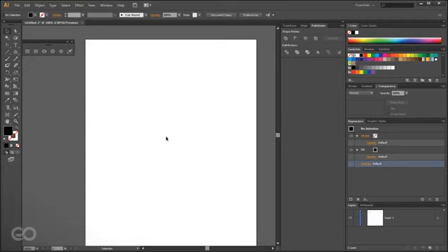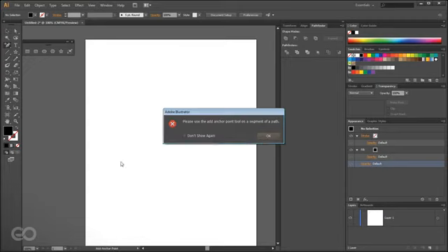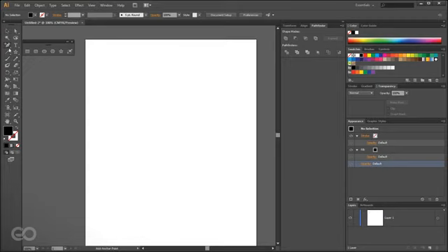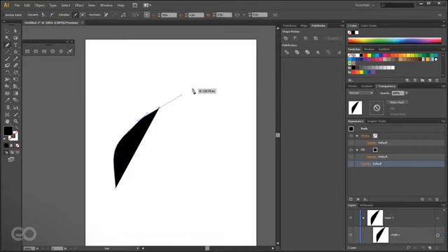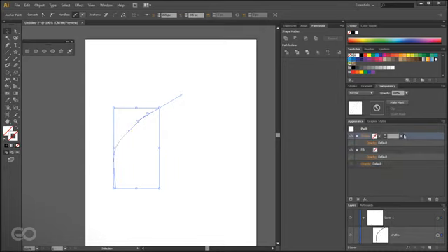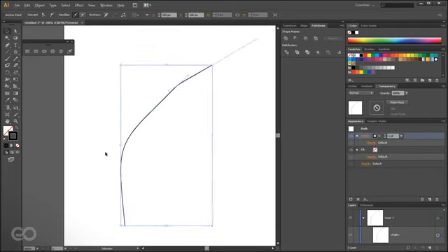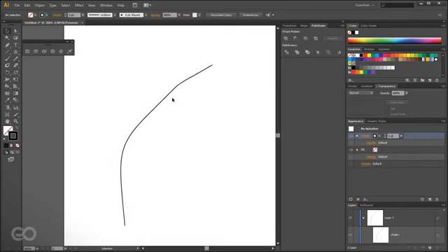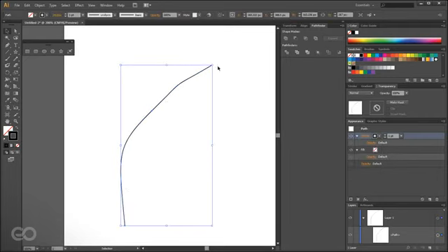I'm just going to show you one last thing here, which is if you have used the pen tool, and let's say you only wanted the stroke, not the actual fill, I'll go ahead to the fill, remove that, I'll go to the stroke and apply a stroke to this. Now let's say you wanted a stylized stroke, you wanted different widths or different outline settings.